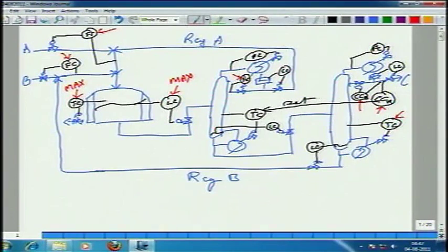On the other hand, if you allow too much C to leak out, the extra C that is floating around will cause the boil up here to increase, will cause the boil up here to increase. You know, there is a cost associated with recirculating something round and round. Yes or no?